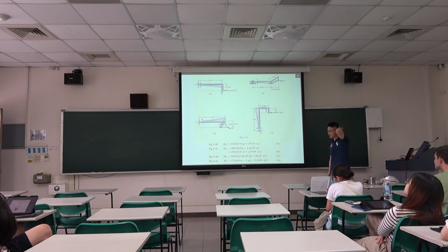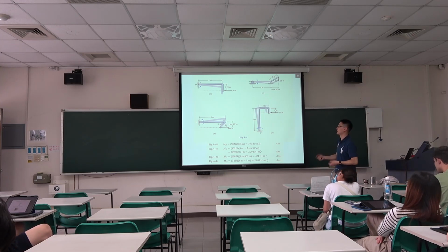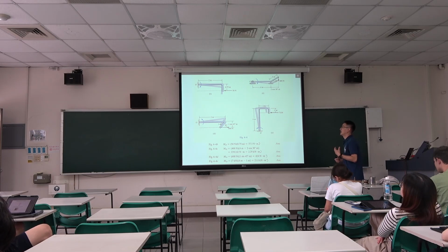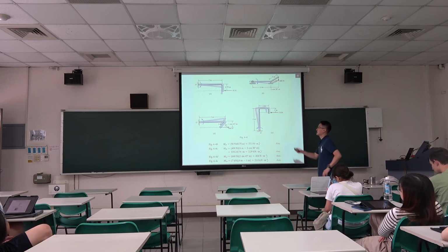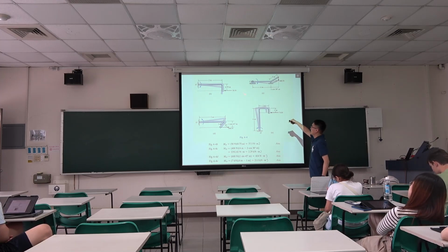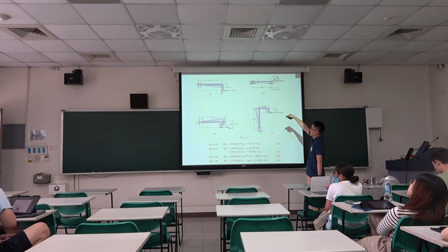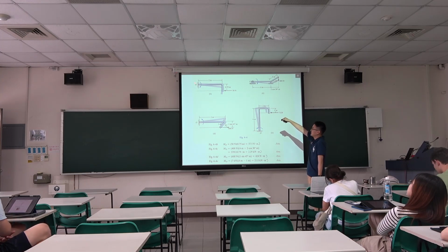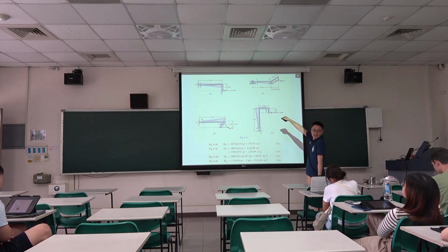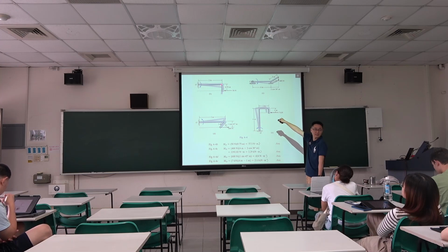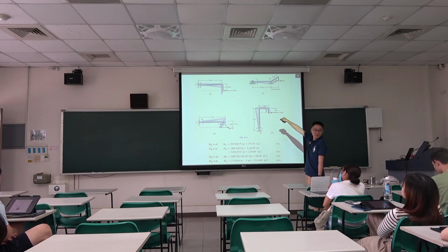I will not say those practice questions are difficult, but we just need to judge the direction, and particularly the lever arm judgment is important. So we look at question B, loading 50 Newton toward the left, and to reference point O, the lever arm is 0.75. Perpendicular distance, perpendicular to the force direction.